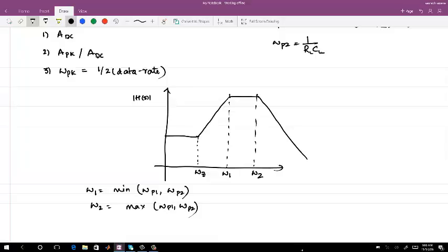And the parameter which we want is this, which is the A peak by A DC. This is a DC value. So the question is, in what other manner can I achieve this? I can also use this, right? The requirement is that I should have this peaking value at your Fs by 2 frequency.